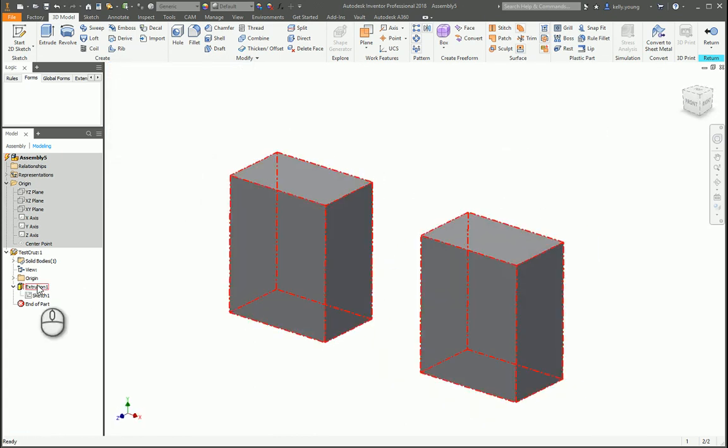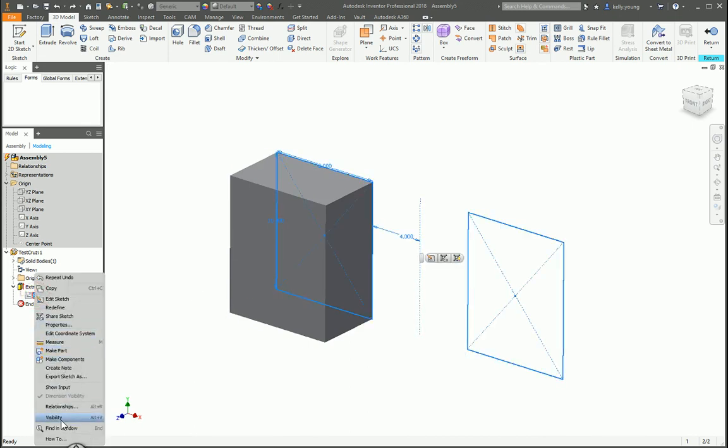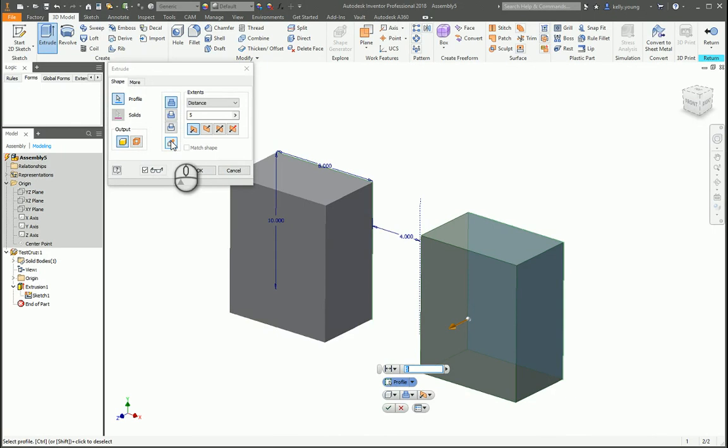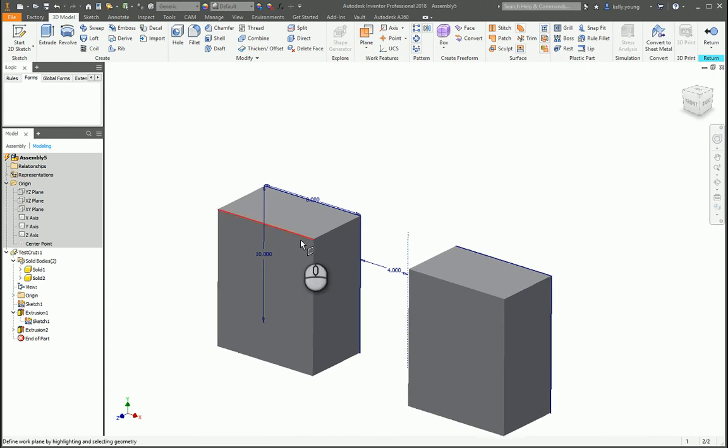It's all one extrusion. Now, instead, let's say we go to visibility, we would extrude this as a new solid. Say, okay, so now we have 2 solid bodies that are different. So if we wanted to, let's make a plane off of here at 8.